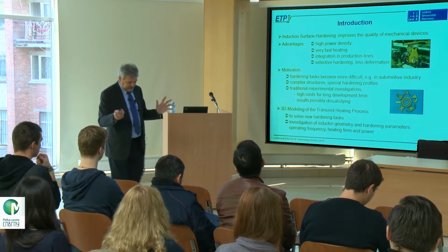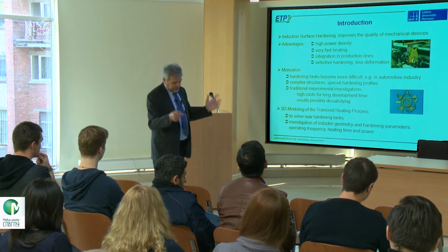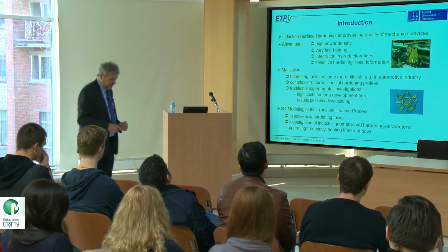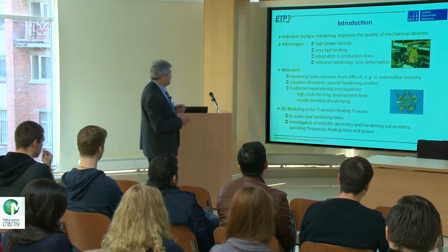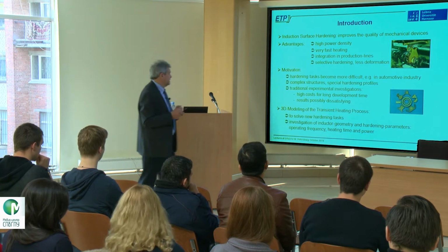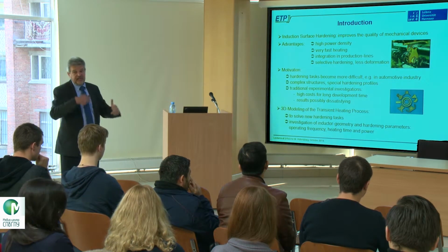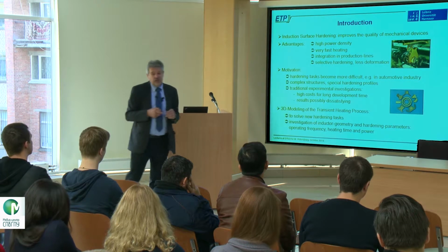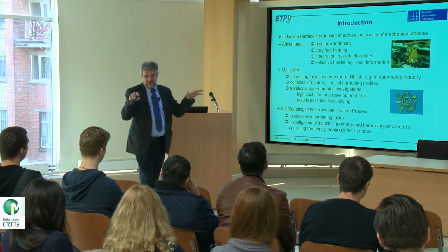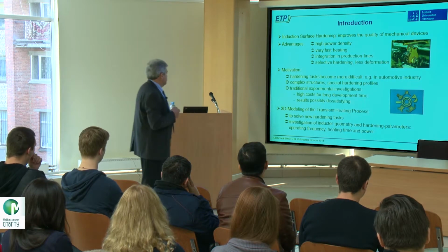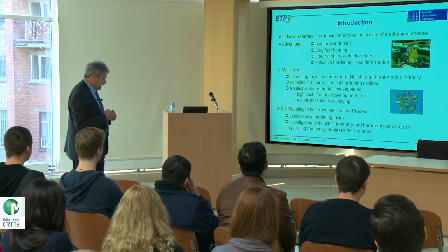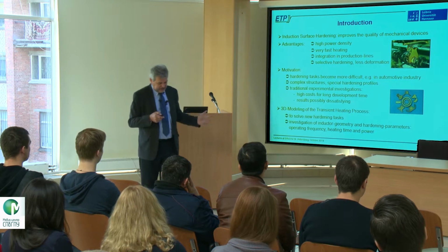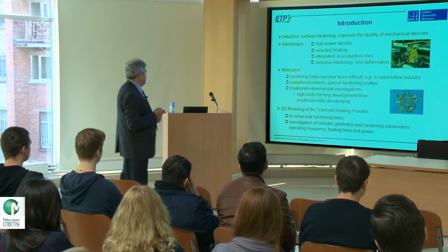If you go to these treatment furnaces, your parts have to be heated everywhere up to 1000 degrees centigrade and then cooled down. But this means that you normally have quite strong deformation. And this has to be finally corrected by mechanical deformation or by mechanical tooling afterwards. If you use induction hardening, the deformation is much less, and this is also one big advantage besides a very short heating time, process time.